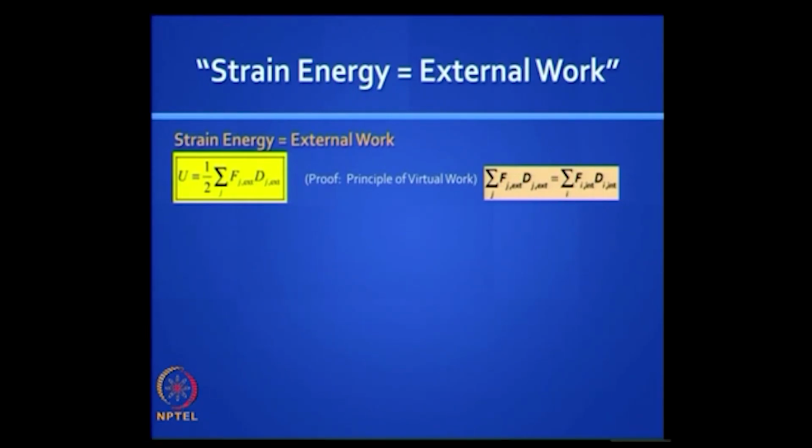Now one of the theorems which is sometimes very useful to apply is the concept called the external work done. When you load a system gradually from 0 to its maximum value, the external work will be equal to the total internal work. Remember, if it is a linear elastic system, the factor half will apply also to the external work. Okay. This is different from virtual work, this is real work.